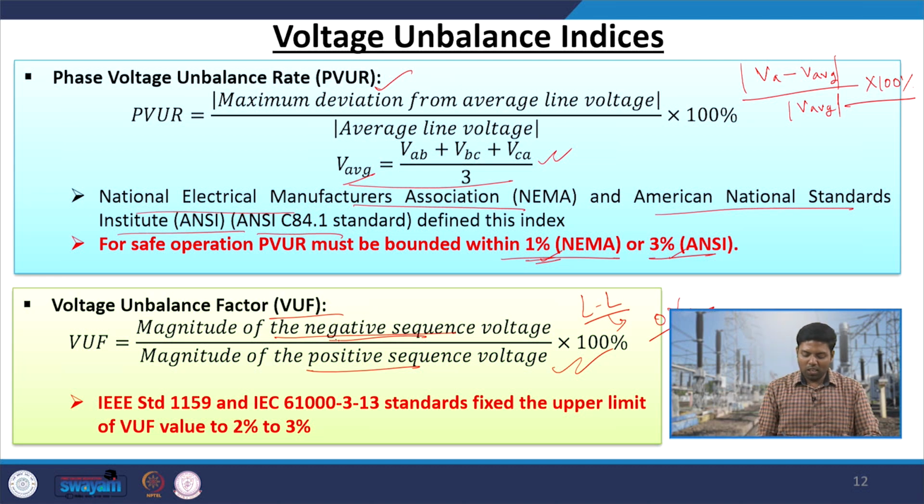That is why we take the negative sequence, because any kind of faulted or unbalancing effect always gives you the negative sequence, while positive sequence is always present, in balanced condition and in unbalanced condition. On top of it, if you have a negative sequence component, then we will say that the system is incurring unbalanced operation.